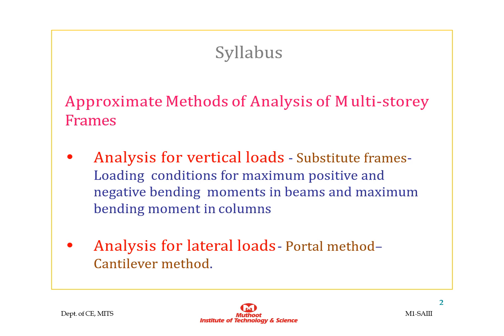In this module, we are going to analyze multi-storied frames for vertical loads as well as lateral loads or horizontal loads. For the analysis of vertical loads, we use the substitute frame method, and for the analysis of lateral or horizontal load, we use the portal method or cantilever method. So totally there are three methods that we are going to discuss in this module.